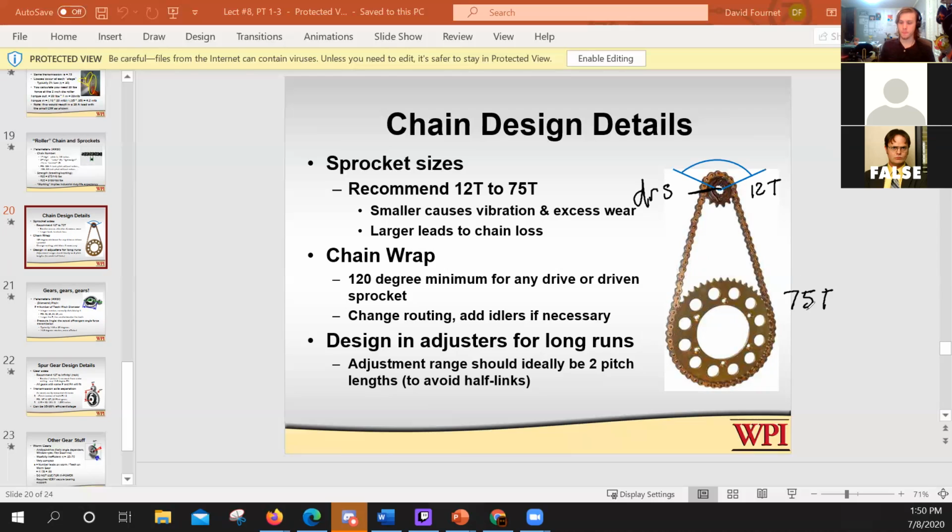The one with the 12 teeth, the driver. So this one's faster, and which one's going to have more torque? The one that's not driven. So this one over here is going to have more torque. Yeah, I'll put more above it.